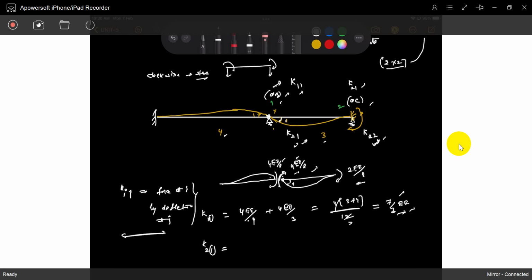How much force is transferred if you apply it? If you apply a joint minus 20 here, plus 30 here, half of it transfers here. Moment distribution method, we already discussed. For this total joint, 50 is required. We add 10, 20 here, 30 here based on the stiffness.